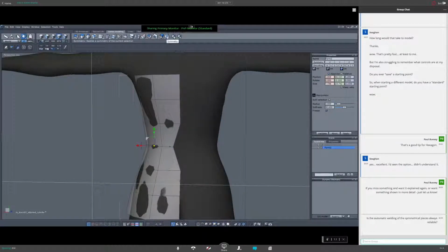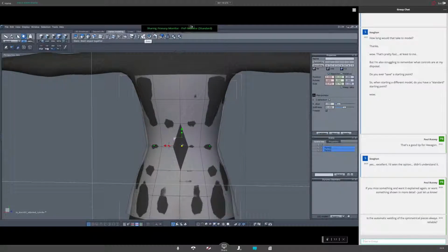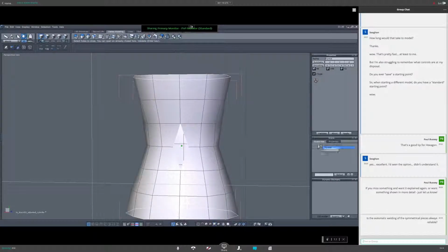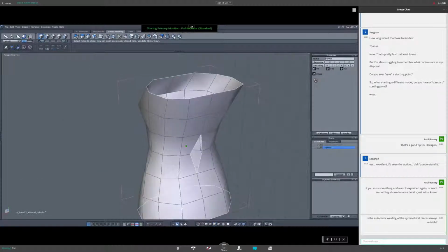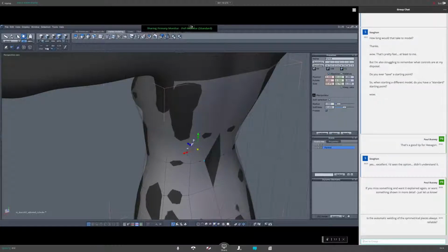Now we are welding these. Now when I hit close, of course it will show me this white outline here that there's a gap. You don't have to validate here. I really recommend you don't. This is just for showing you the problems. You go to abort. What you have to do in this case is to select these 2 points, use the scaling function to pull them together. Like this.